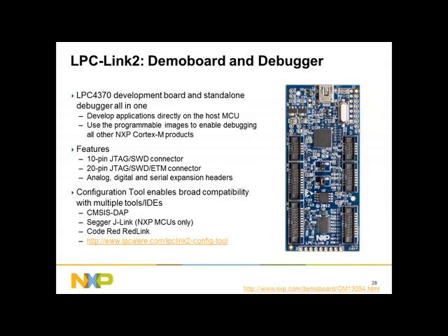All right. In terms of development tools, this 4370-based Link 2 board is kind of a cool thing. It has multiple uses. It is a 4370. You can see the small 100-pin package there in the top middle of the board. Now the 4370 in the 100-pin package you can use as a development board with this Link 2. So if you bought a Link 2, you could hook up your debugger and do some development work for the 4370 based on this board.